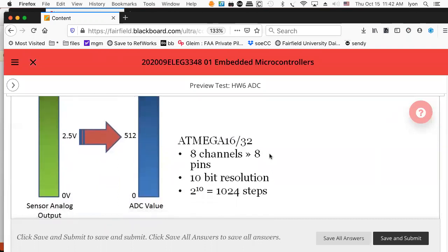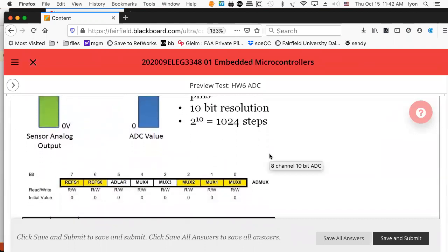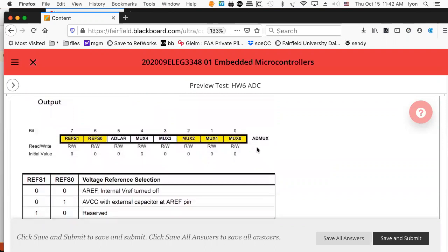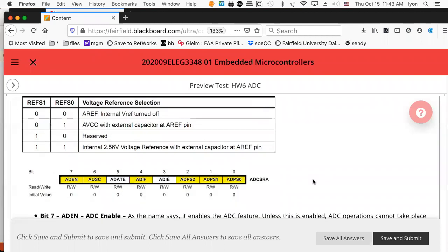And I think we saw this as well. And here comes our good friend ADMUX. And here's the reference, analog reference inputs. And if you put 0, 1 into the most significant 2 bits, you're going to get VCC as your reference. And we now know why.